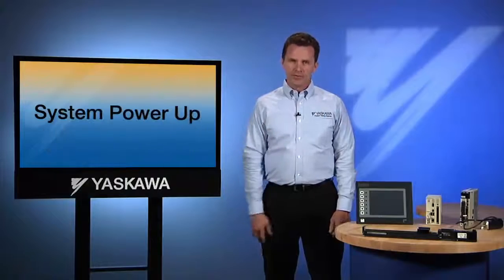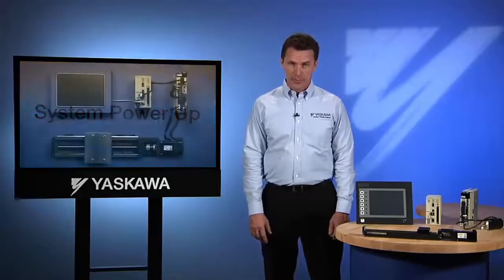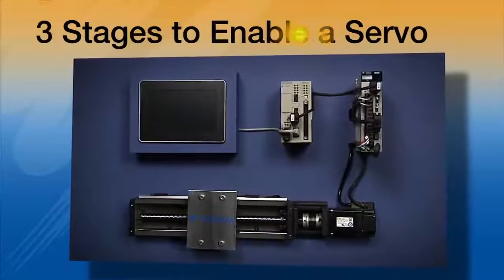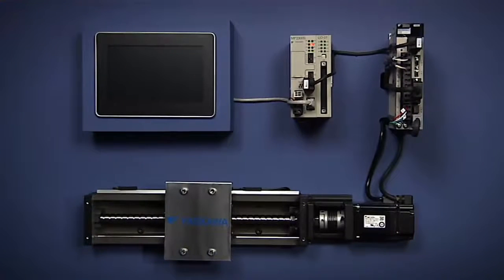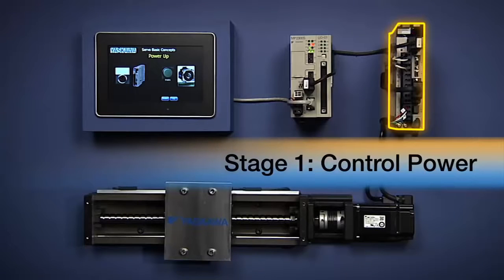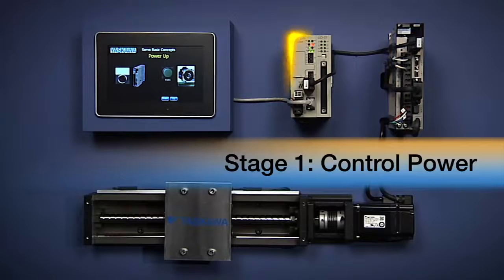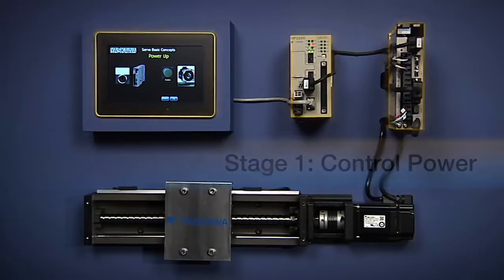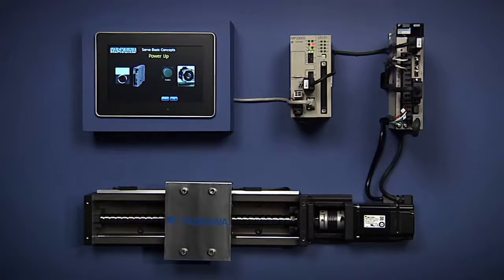Turning on a servo isn't as simple as switching on a light bulb. It's important to know that there are 3 stages to enable a servo. First, the amplifier itself must be turned on. We refer to this as control power. The system is typically wired to power up the controller and the operator interface at the same time servo control power is established.